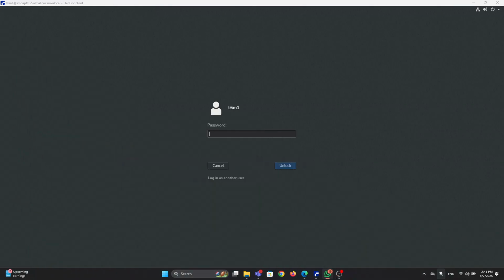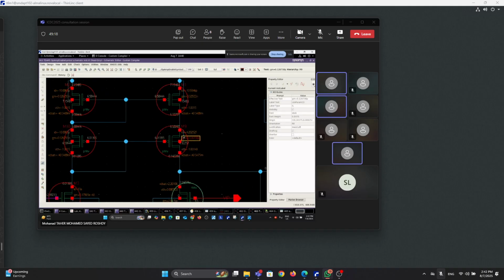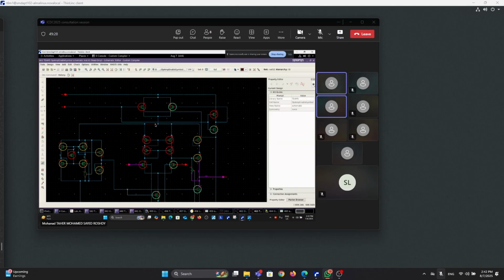By the way, Mohan, I think I see something. You go back to the schematic a while. Maybe you need to confirm with Daniel as well. If you zoom into your current log for the op-amp, the first stage, the second PMOS there, the body should tie to VDD as well, right? Yes. Oh yeah, right. This one should go to VDD, the highest potential, the supply voltage.